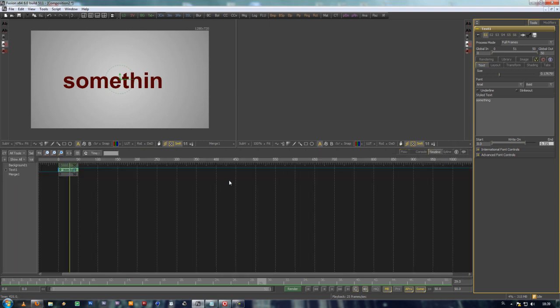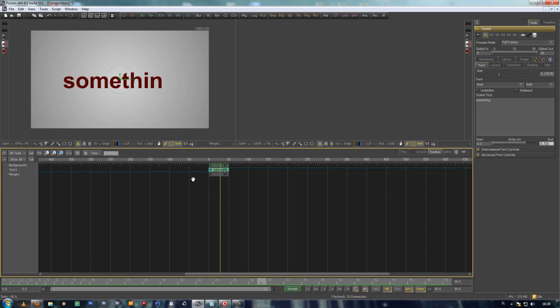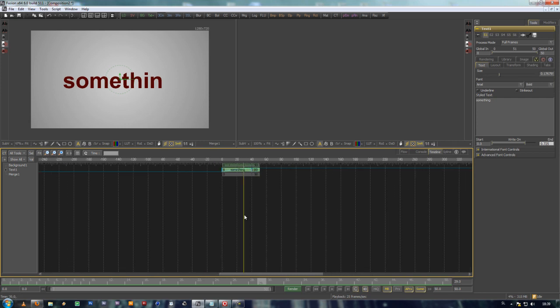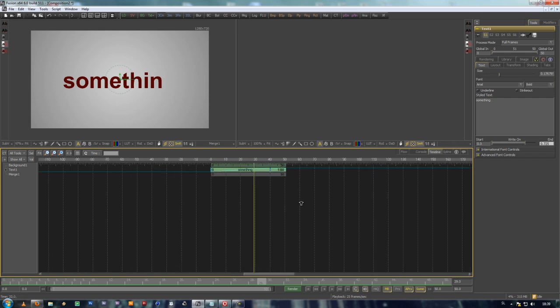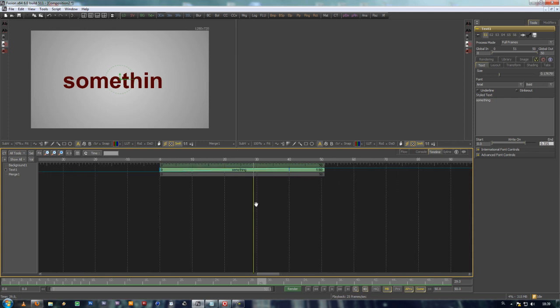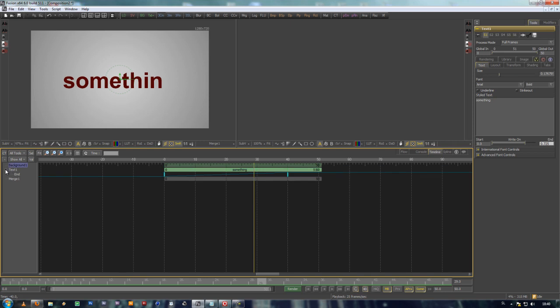In the timeline you can of course zoom in and out like in viewport. So that's middle mouse button, hold it, click left mouse button and drag left to right for zoom in, and the other way for zoom out. And if you click here on plus button, you will see our keyframes, start and end. You can move them if you want to over here like this.